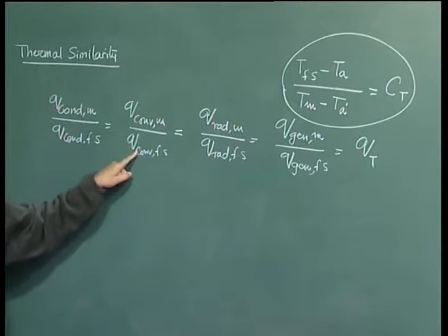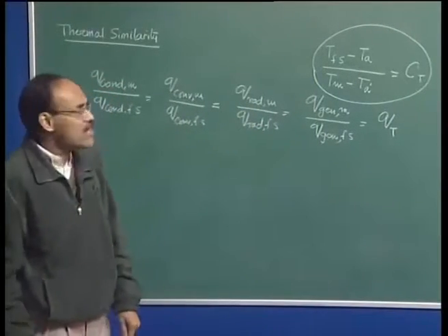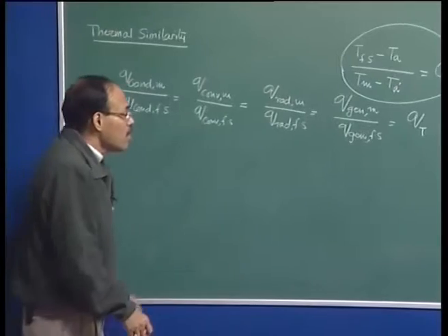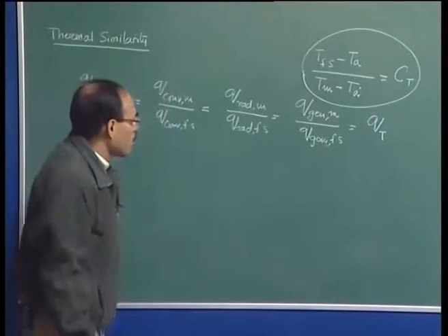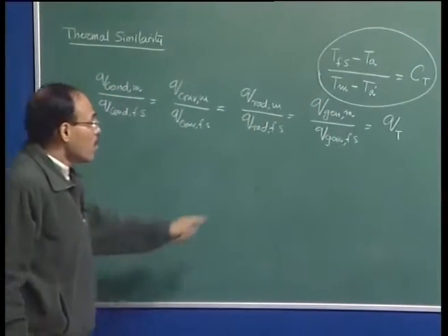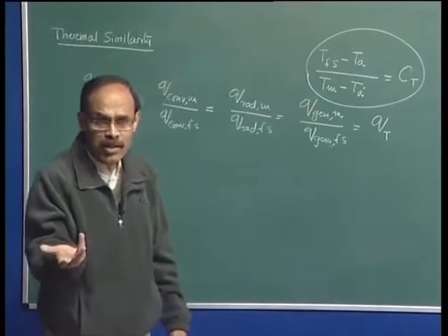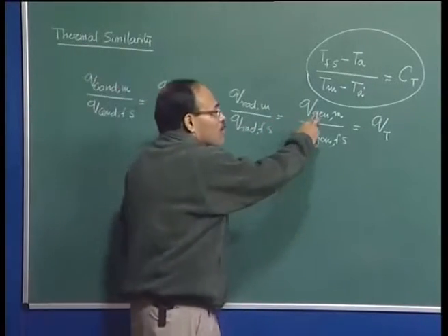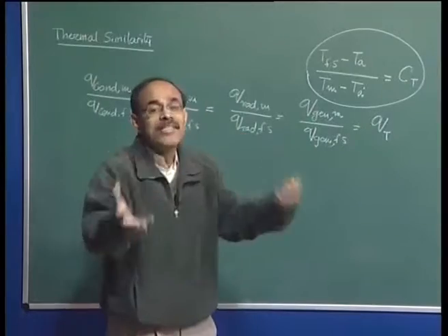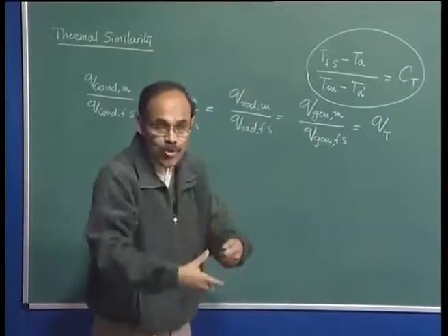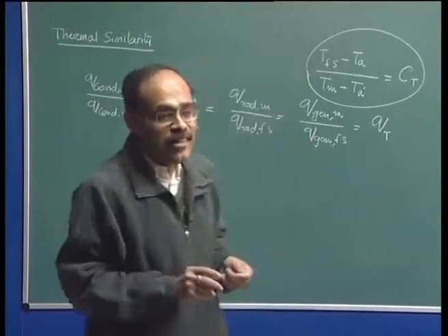Now, we know about these three components because heat is transferred from one point to another point by three different mechanisms. In steel making, molten steel making systems, or in vessels containing molten steel, within the bulk, radiation may not be important. Radiation is important only from the surface, from which the melt loses its temperature. What is this generation? This generation is in fact some heat evolved maybe because of chemical reactions, for example, or some heat consumed. So, the generation can be visualized in terms of a dissipation also. If it is a positive generation, then that means it is produced. If it is a negative generation, that means it is going to be consumed, and this consumption of heat in the system can be because of, for example, a chemical reaction taking place in the system.